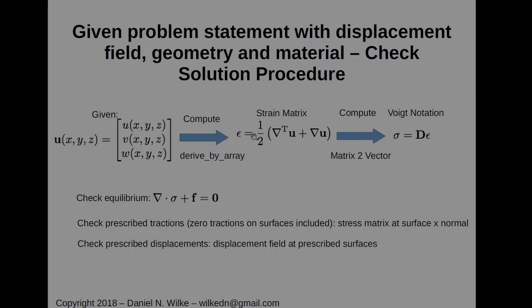And now I can say, well, we know that this is symmetrical. So instead of having 9 components in the strain matrix, we can package them using the Voigt notation into a 6x1 vector. That's in any case what we need to do if we want to use the classical constitutive matrices, especially the matrices that are also supplied in the prescribed textbook. So let me maybe just quickly see if I can open up that prescribed textbook, just an example of that maybe quickly.